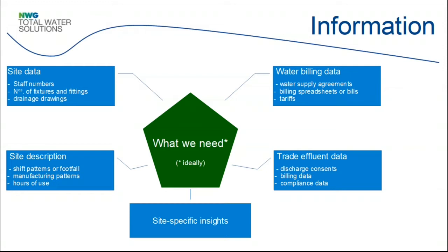So we take that information, and one of the things we do is we have quite a sophisticated procedure to take things like estimates of staff numbers and turn them into predicted consumption patterns that we can then compare with benchmarks. And this can help to show you savings that can be made by changing, for example, equipment such as systems or tap mechanisms or showers or pressure washer settings or pressure reducing valves. And they can be very useful for showing where the financial savings can potentially lie.